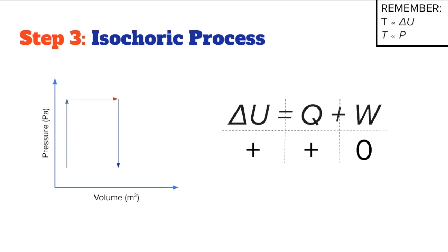Due to the identical shape of the can, we can say that there has been 0 work done, which brings us to figure out the change in internal energy. Seeing as the only thing that is left in the can is steam, we are continuing to add heat to it via heating by the candle. This means that the change in internal energy is positive, with the increase in temperature and energy added to the system would also be positive.